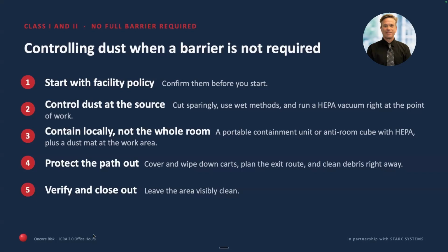One thing I'd like to remind people of when you develop the ICRA and you develop your containment: remember you're going to have to contain spaces just outside the construction area as well, going out to the dumpster or other areas. You need to look at those types of things depending on the risk to the patient. So these are the things that we do in 1 and 2.